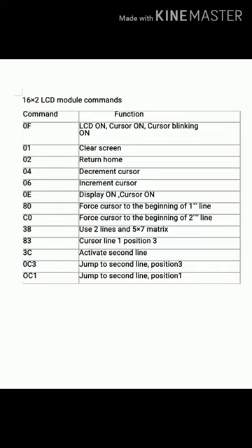That is one probability. The second probability is that the data you have sent might be data that you want to display. In that case, the data which has come gets stored in the data register, and once it gets stored in the data register of the LCD, it gets automatically displayed with the given configuration. So RS is the signal which comes from the microcontroller to the LCD unit, and whenever the LCD unit receives 8-bit data, it waits for RS to come from the microcontroller.